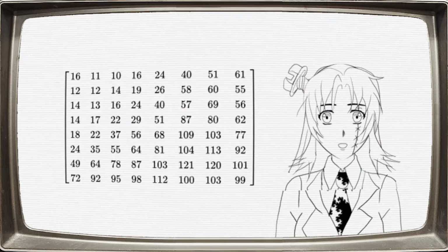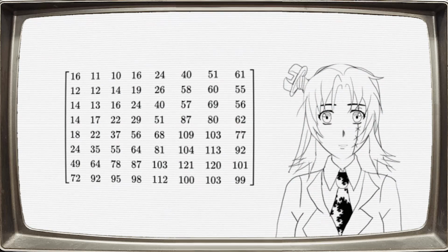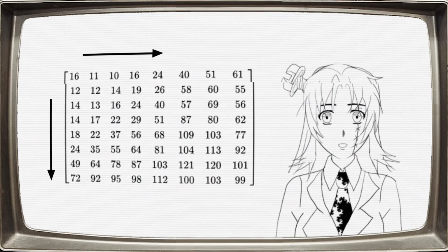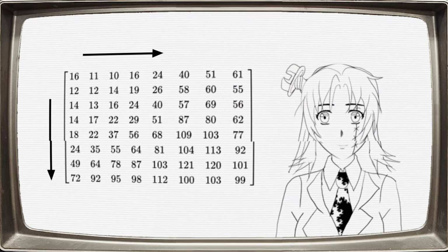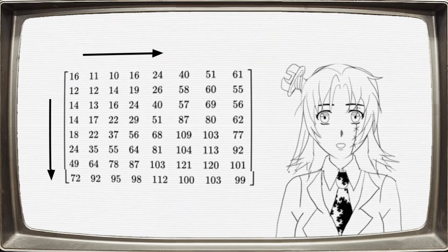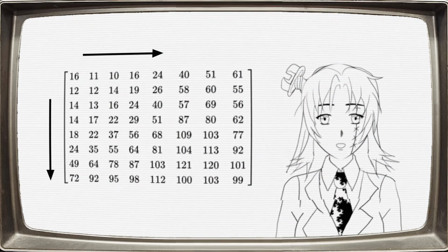As you can see, if we do this, a lot of the values become 0, which means they are discarded. You may have noticed the value of the quantization matrix becomes larger as the frequency of the cosine waves increases. This means high-frequency waves are more likely to be set to 0 than low-frequency waves. This is due to the fact that our eyes have trouble perceiving high-frequency change in brightness or color.